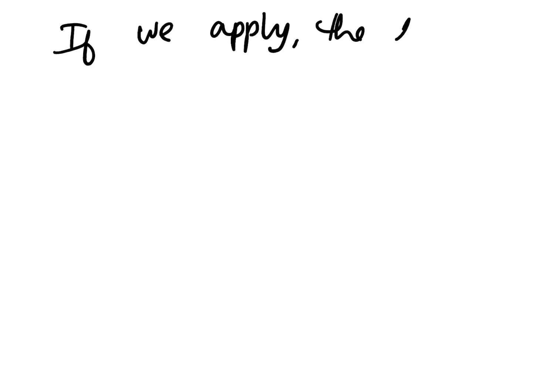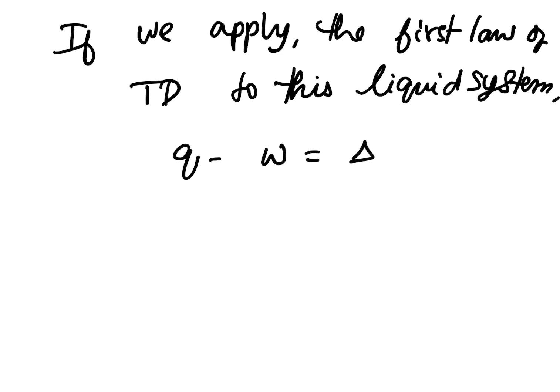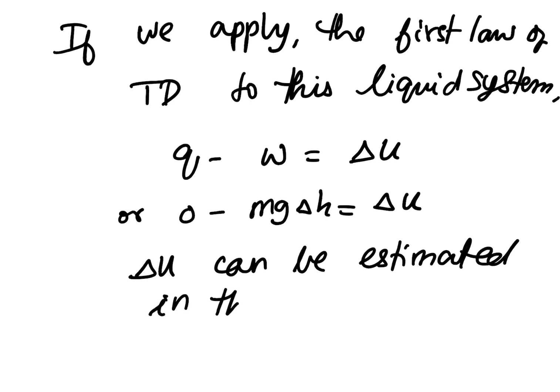Okay, so if we apply the first law of thermodynamics to this liquid system, what do we have? Q minus W equals delta U, or 0 minus mg delta H equals delta U. Now what you should take away from this equation is that delta U can be estimated in this experiment.